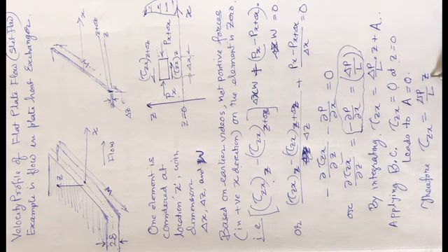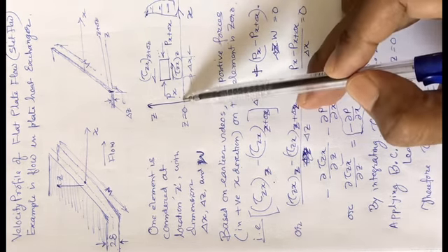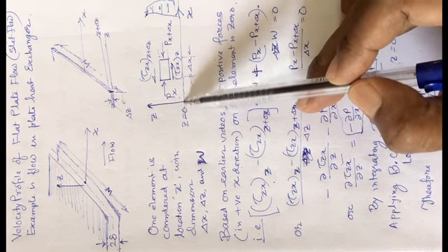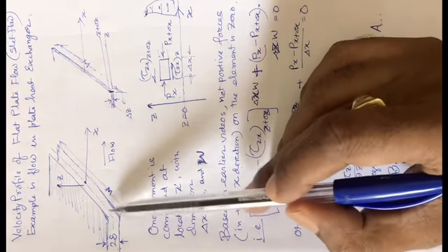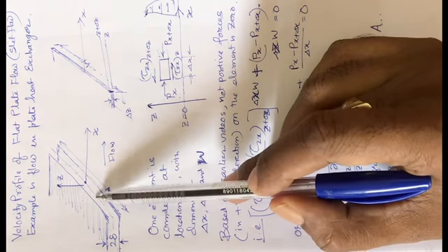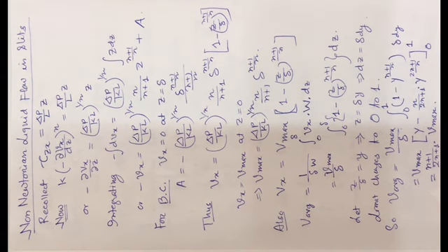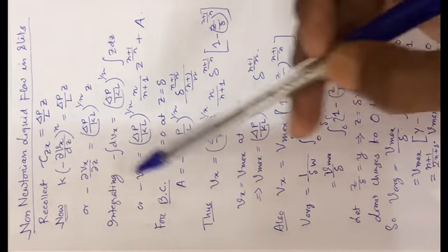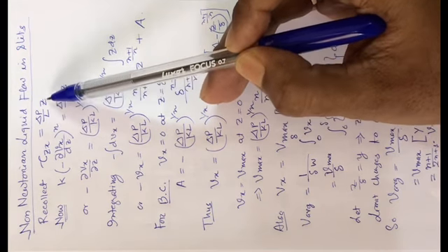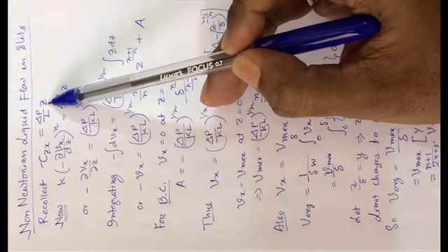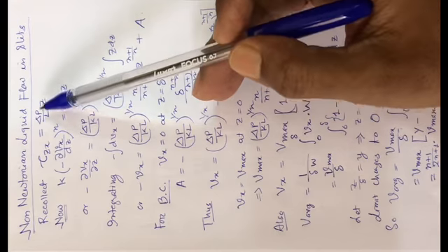Okay, z means position. You will have to measure that position with respect to the midpoint of this particular gap. Okay, so there is a central plane. From the central plane we will be moving upward. That is it. So what we have seen is that the shear stress depends on the pressure gradient and z. Z is the location with respect to the central axis.